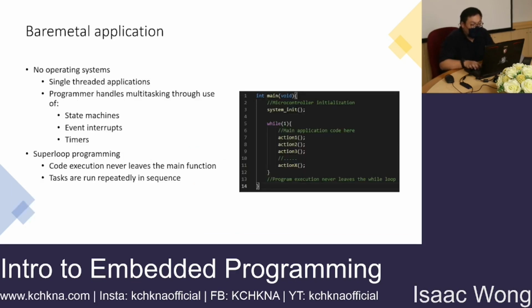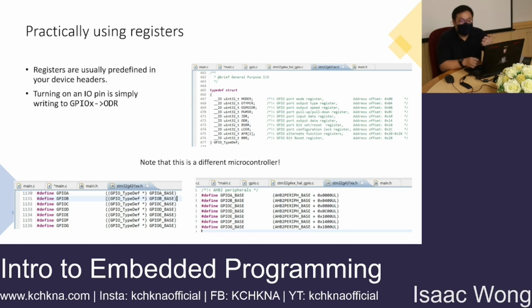Now, to be even more practical, I don't usually address the register directly like this. I use this thing called HAL, that's a hardware abstraction layer. Manufacturers usually provide drivers for different peripherals. You can use this driver to actually do things with the peripherals without having to meddle with the registers itself. What this does is your code becomes portable, such that I can switch out the hardware, but even though registers are different, I don't have to change my code because it's the driver itself that changes.